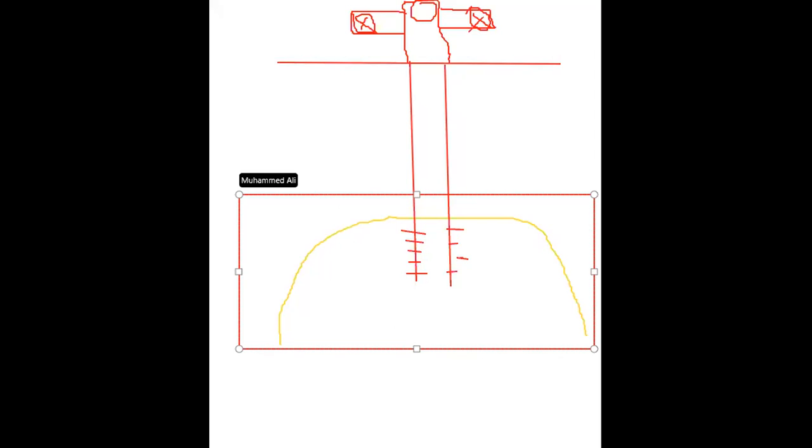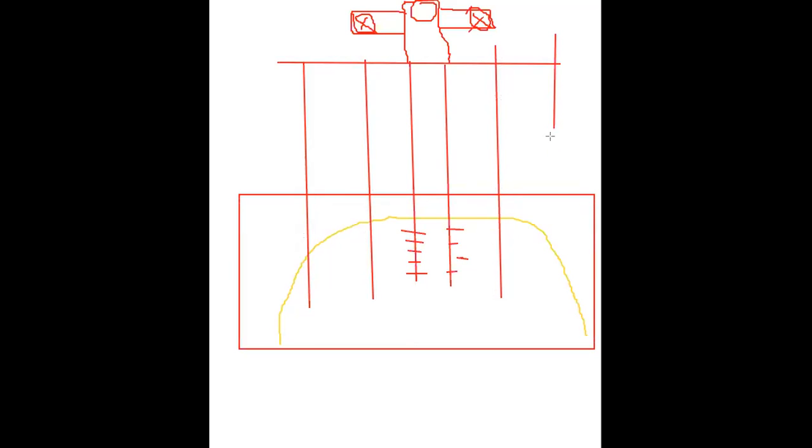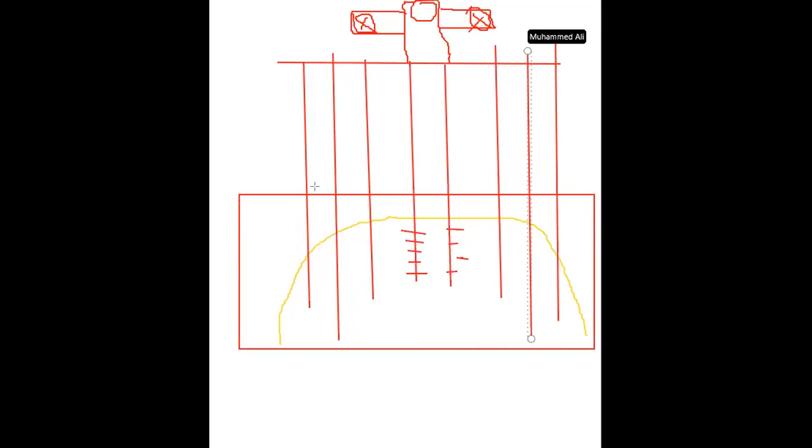The second reason we want to know reservoir fluid properties is because we want to know how we can develop a reservoir. Developing the reservoir basically means how many wells you are going to put and where exactly you are going to produce from. For example, you can put this well, or this well, or like 5 wells here. How many wells you need to put in this reservoir and at what depth. So in order to find the total number of wells in one reservoir, we need to know again the fluid property.